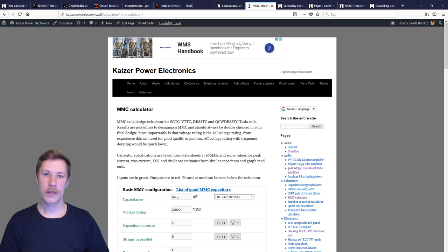So I would certainly stick with larger through-hole component MKP capacitors, simply because they can be soldered to some bus bar or something to take off the heat. But I would really recommend that you try it and write about it on forums, so other people can learn from your experiences.